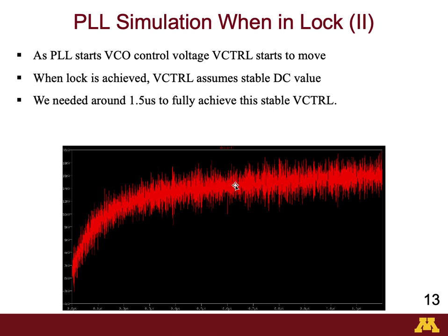Yet from the average level, we can see that after running this for a long period of time, it stabilizes. I have just given a screenshot for not so long a period of time, but if I run it for much longer, then it actually stabilizes at a certain level, giving us the scenario where VCTRL is fixed and the phase difference between the PFD inputs is also constant.